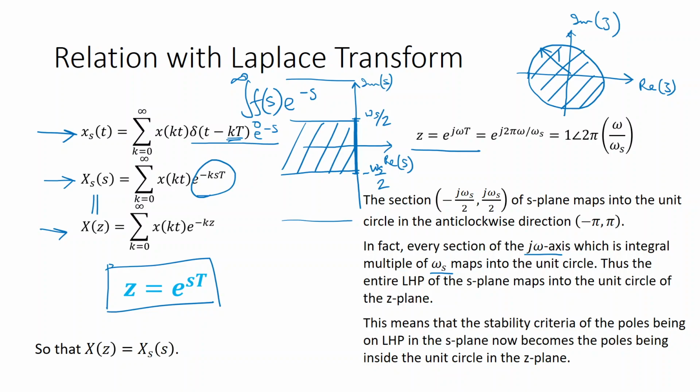So the entire left half plane of the s plane is getting mapped into the unit circle of the z plane. That is an important idea to capture.